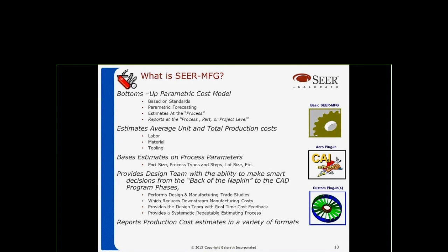Basically, if we've collected standards, let's say a welding, to weld 1 inch of a weld seam, maybe 2 inches, maybe we collected 3, 5, 7, 9, infinitum. And what we do is we'll connect those dots using a least squares projection. And if a user comes in and wants to know what the cost of 2.5 inches of weld is, the model will report that out based on that parametric forecast in between the 2 and 3 inch absolute time study that we have.